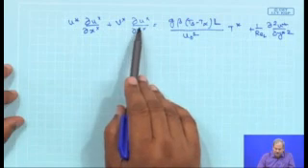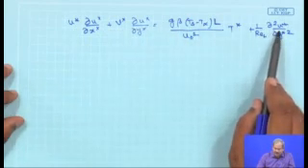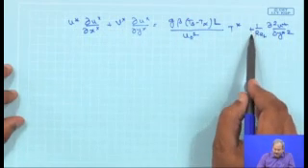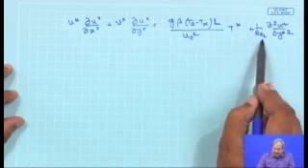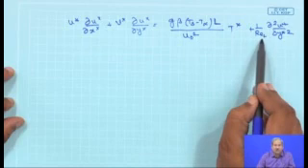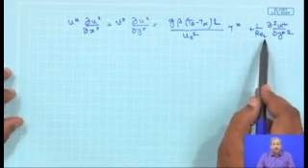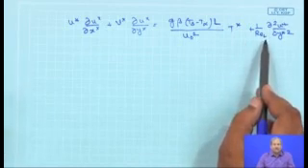So, these two terms will remain and this term will remain as well, and you can clearly see that the similarity parameter for such a case, as we have seen countless times before, would be the Reynolds number. So, for a situation in which there is no temperature difference, natural convection does not take place, and the equation of motion will have the known similarity parameter as Reynolds number only.